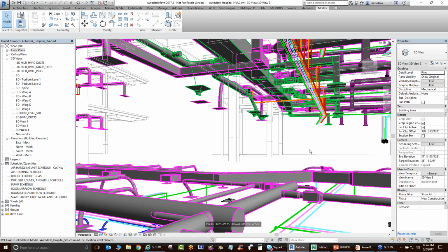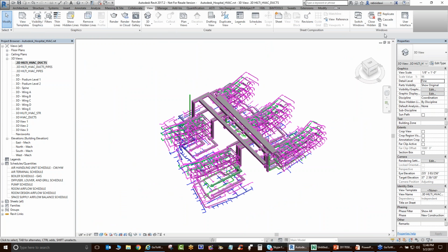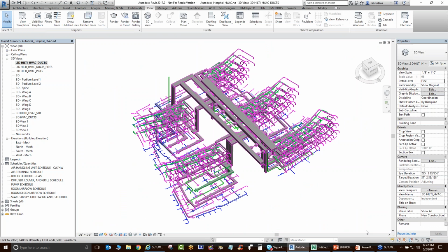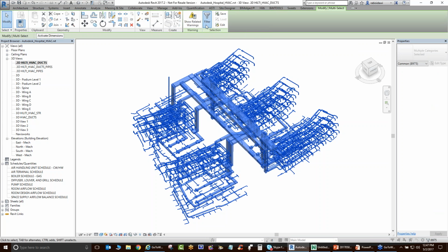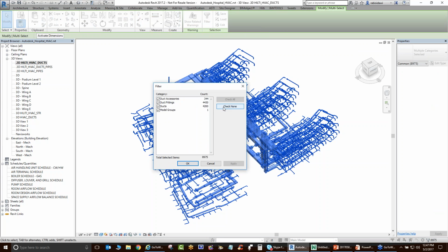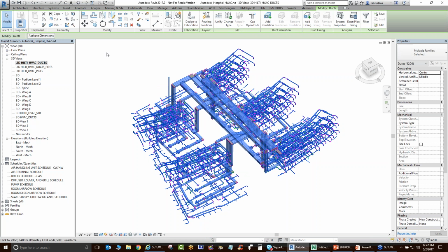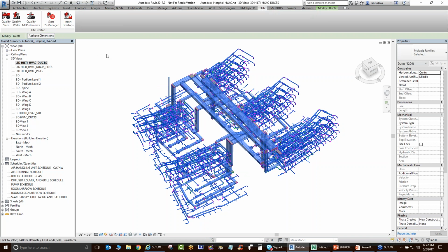All right, based on that, we're going to let the software do the hard work for us. So I'm going to switch over to a 3D view. I'm going to close down hidden windows and zoom in on this duct model. Let's see what's in here. So let's make sure we have the proper categories. We want to make sure that using the selection filter inside of Revit, we'll be able to select specific items such as ducts only, for example. These are the ones that penetrate the slabs and the walls. So we'll use the HILTI button for Firestop add-in for Revit, and start by qualifying MEP elements.